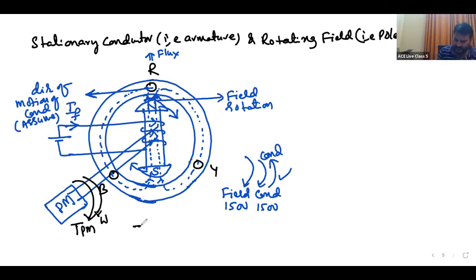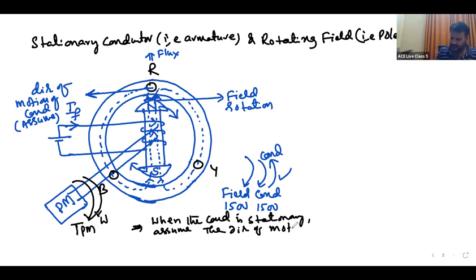That is correct. Remember: when the conductor is stationary, assume the direction of motion of the conductor in the opposite direction to that of the field rotation. Let me write that.